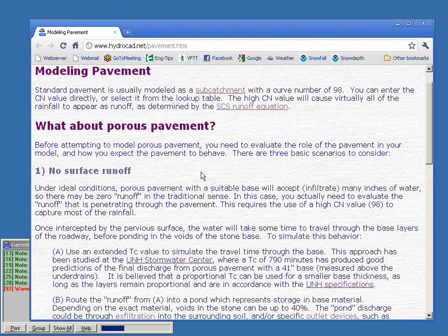If you're setting up your HydroCAD model primarily for peak flow management, then you may find that many of these LID techniques have a minimal effect on what's happening during that 10 or 25-year storm. You may also find that your local ordinances don't want to allow for the porous pavement in the management of the 25-year and longer event. They may want to be sure that they're dealing with a worst-case scenario where that pavement may be frozen or otherwise plugged, poorly maintained, whatever it might be.